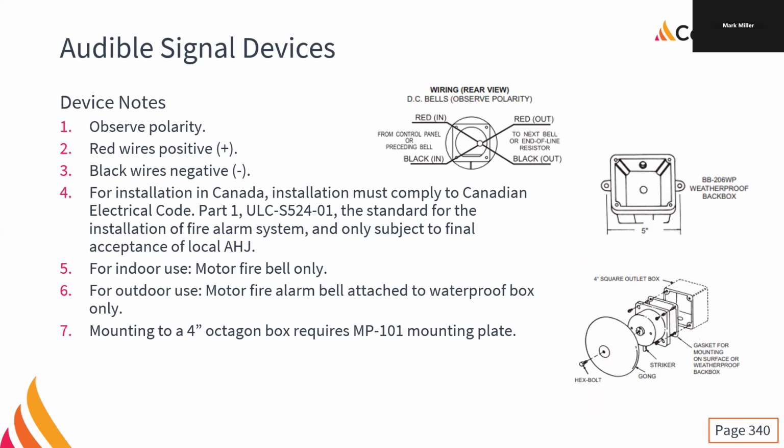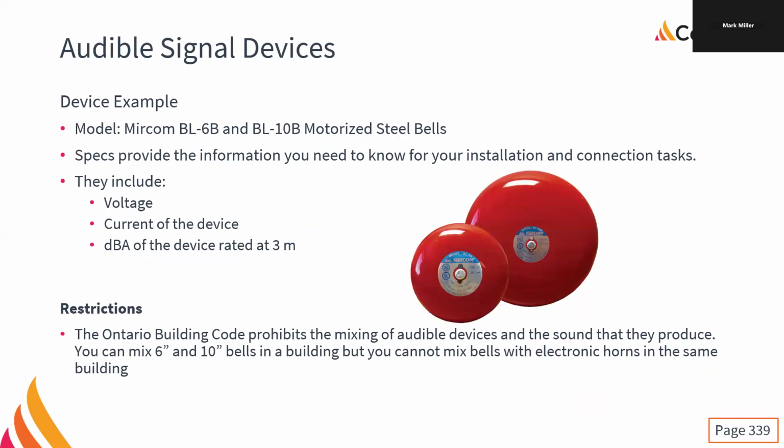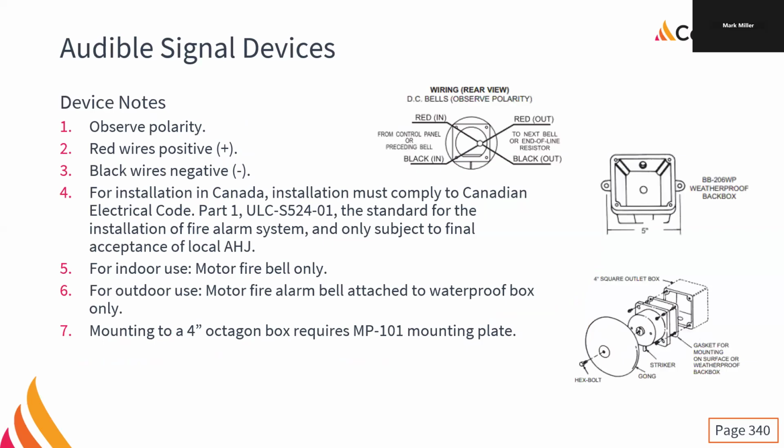If we go with the 10 and the 12-inch bells, we have to be considerably lower, because the bottom of a 6-inch bell is the same distance from the center of the box as the bottom of the 10-inch bell. They move the center line of the bell up, because the back portion of a 6-inch and a 10-inch bell is identical.